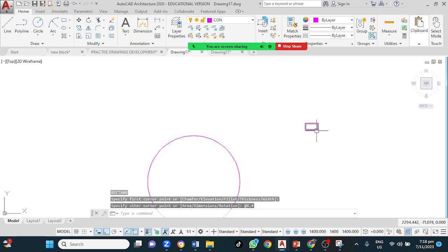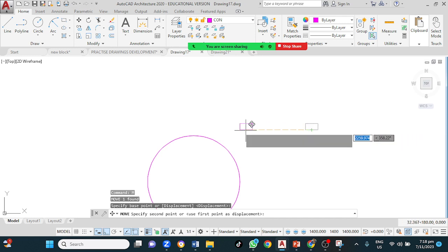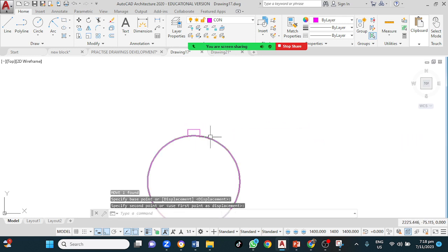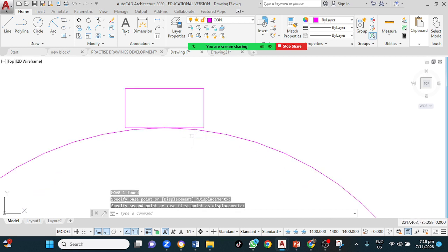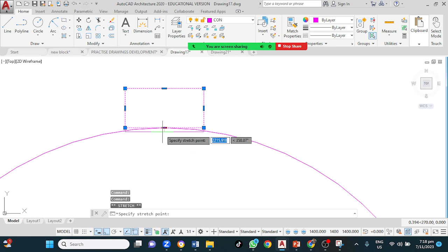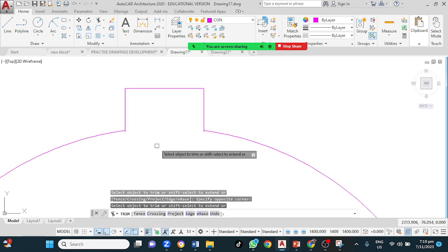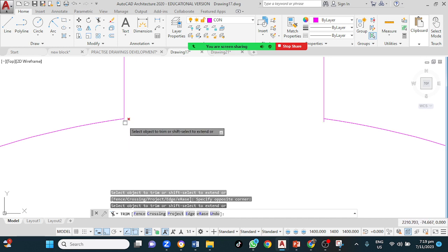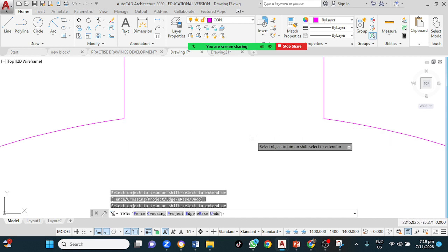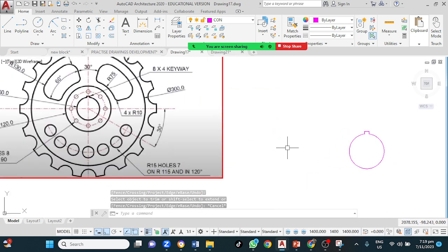And we then move it. Left click, top quadrant. Enter. And we drop it here, right? Top quadrant. All right. So I'm going to move this one a little bit more, I just drag it until I cut into it. Then we trim out this part, right? TR, enter, enter. Left click, drag. Trim, trim. That part is done.